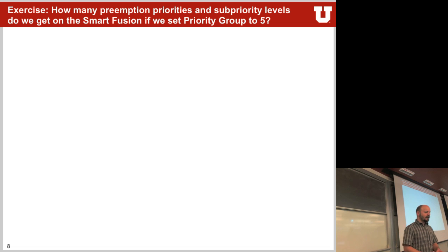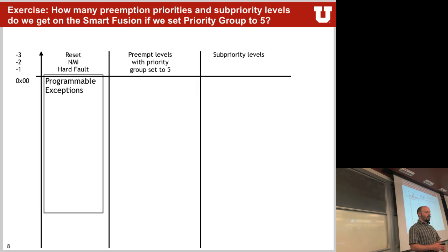This was another one of the questions, and I think a lot of people got confused, so let's start with a little bit of recap and then keep going from where we were last time. What's going on with this whole priority group, subgroup, and how does this really all work? We can have different priorities for different interrupts, and every interrupt can be configured for its own particular priority. Within this priority, you can have the group and the sub-priority itself.